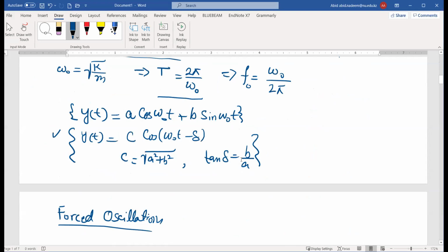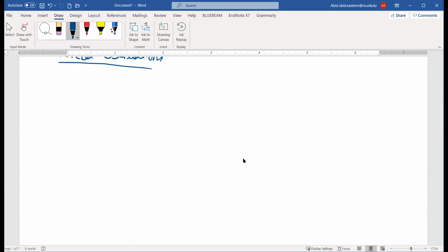If we consider a force over here, this will be the mass, and this will be the weight, and this will be the additional driving force, which you can represent by D. Then there will be the force in the spring, which is represented by K times S naught plus Y, and this is balanced by mg.